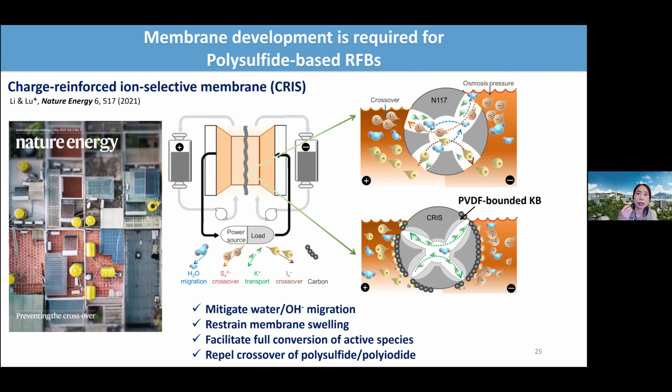And usually, the polysulfide sometimes comes with water together, migrating through the membrane. So to stop this crossover, we decided to have a coating that consists of a hydrophobic polymer-bound carbon. And the role of the hydrophobic polymer, PVDF in this case, is to reduce the water migration and really to reduce the water affinity.